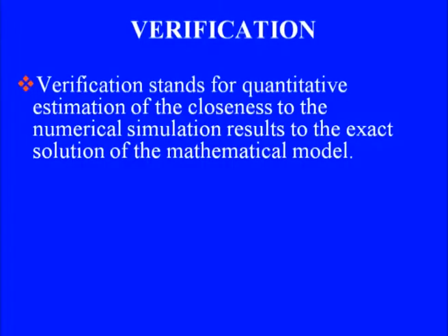So, verification stands for quantitative estimation of the closeness of the numerical simulation results to the exact solution of the mathematical model. So, in our CFD analysis, our first step was we obtained a mathematical model, which was in the form of a partial differential equation or in the form of an integral equation in our integral formulation. Then we applied a discretization process which had its own built-in approximation or errors, and then we solved it using an approximate numerical solution process.